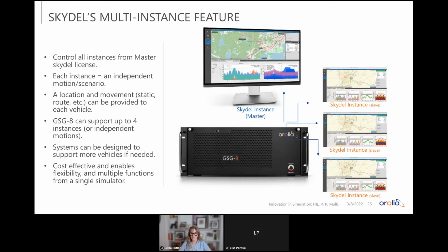But when you're putting it within one system, like a Skydel system, the time sync is pretty much handled for you internally, right? It's part of the system. The synchronization is done. Like in a GSG-8, all four radios are synchronized together internally. So you don't have to worry about externally synchronizing them when you use that type of system.